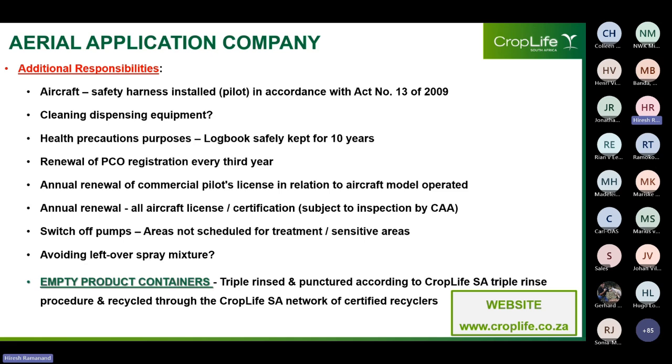With regard to the cockpit or cabin, the pilot needs to ensure that this area is cleaned at frequent intervals. Under no circumstances whatsoever will the clearing of blocked jets or nozzles be done by oral blowing or sucking. This is a sure way of introducing residues into the body and goes against everything I have covered today in terms of personnel protection.